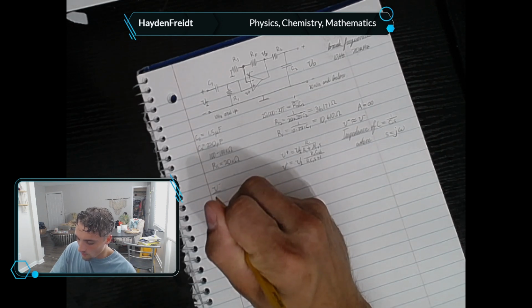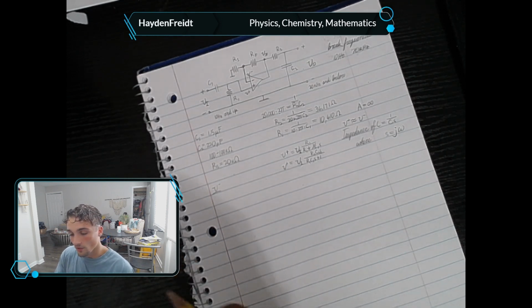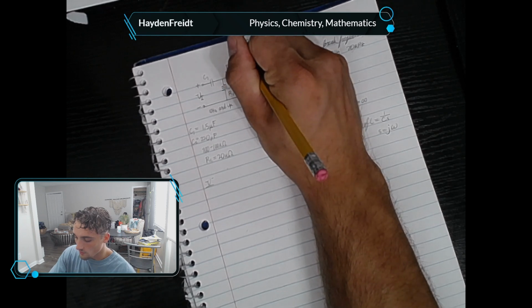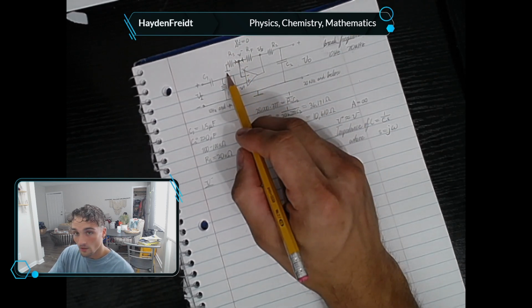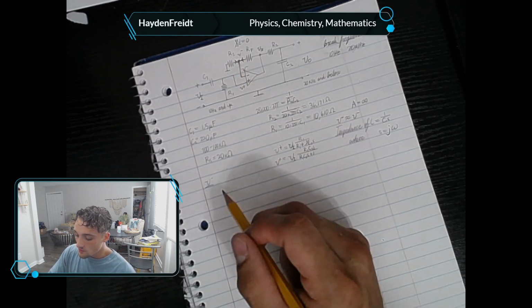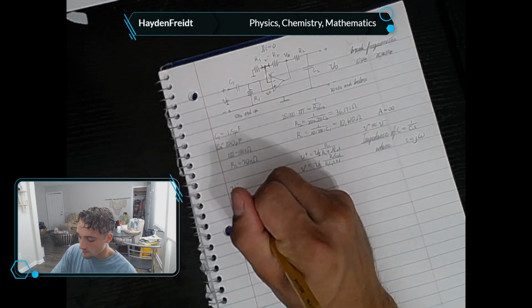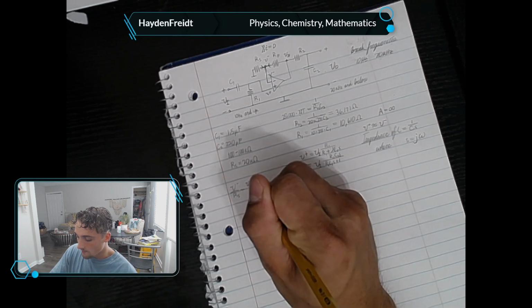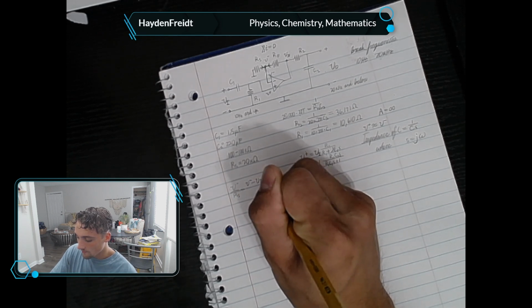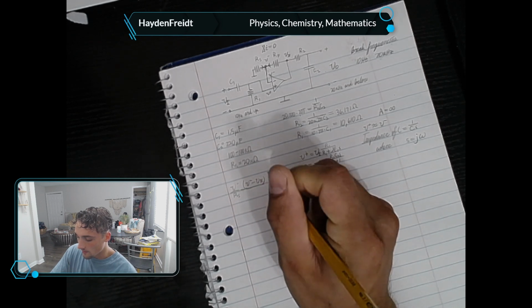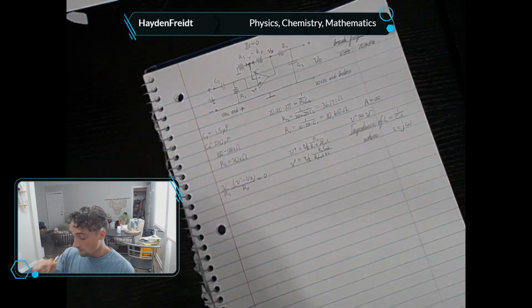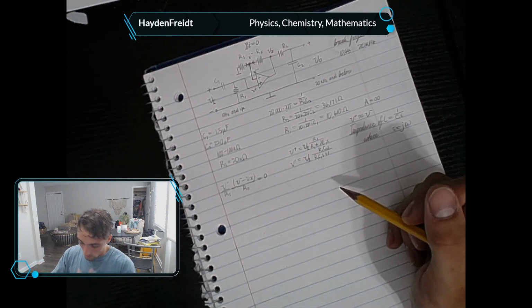This is Kirchhoff's current law, also known as the junction rule. V negative is the voltage across here in reference to ground. Everything's in reference to ground. So V negative over RS, minus, we're going to write it as V negative minus Vx, divided by RF. Let me figure out exactly where I went wrong.